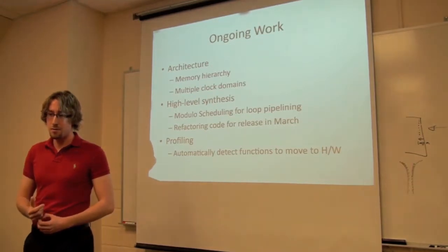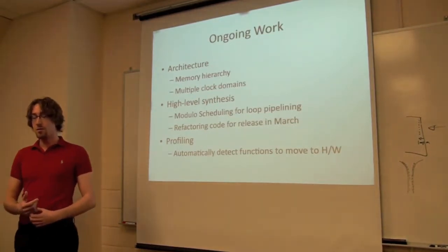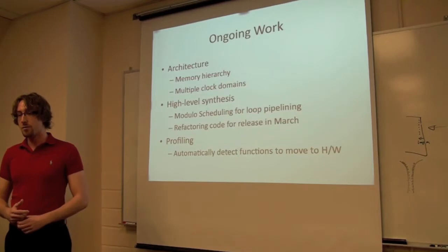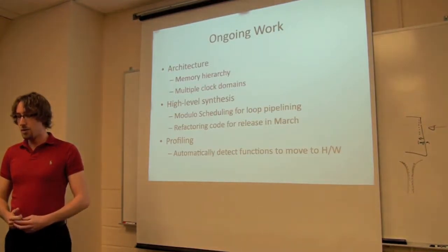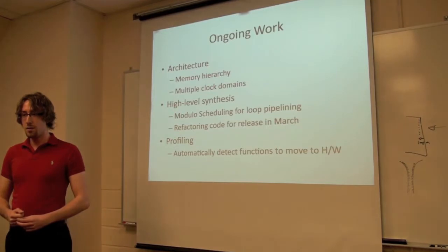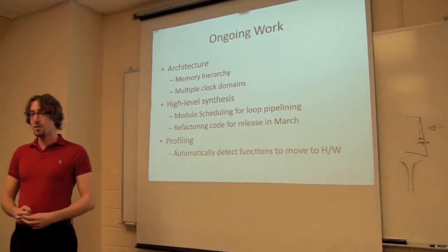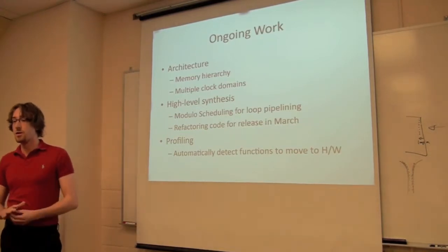Okay, another question about your tool versus Excite, about register usage. You say that your tool tends to pipeline more than Excite. Do you know how much register usage it has compared to Excite? And does it really matter, because the LE count includes registers, right? We do use more registers for sure, a lot more registers.